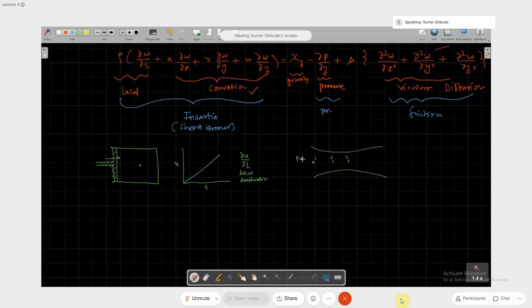Okay. So you have a pressure here, and a pressure gradient is existing, so that you have a flow. You have a higher pressure and a lower pressure, so the flow is moving from left to right. In that case, if you see what changes are happening, initially at point number 1 there will be a certain velocity, and at point number 2 the velocity will increase because it is a converging section. Okay, and then from 2 to 3 it may remain constant. Okay, and then in the other section, say 4 for example, it is a diverging section, so velocity will fall down and drop.